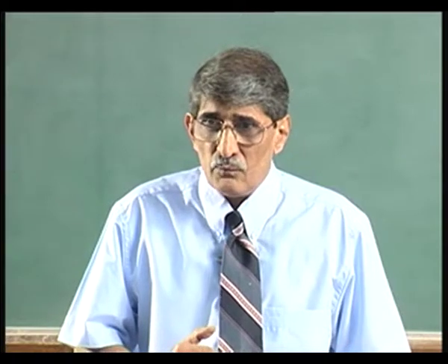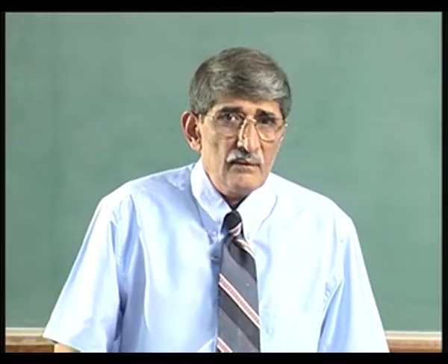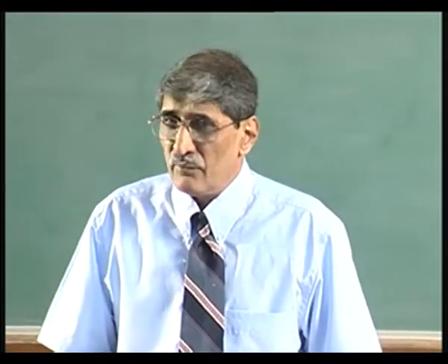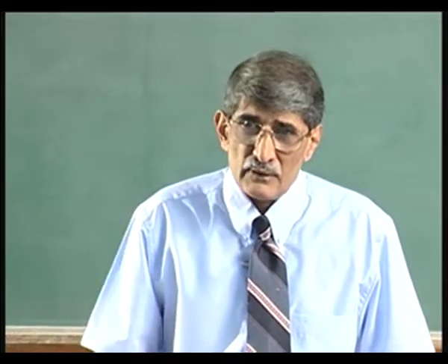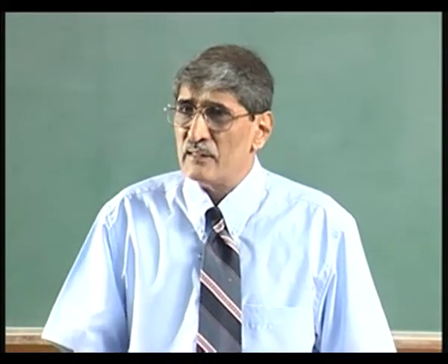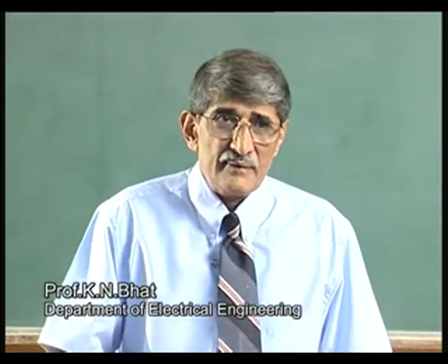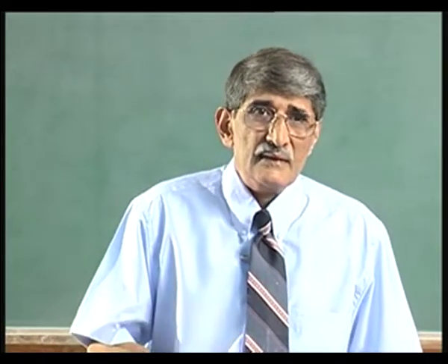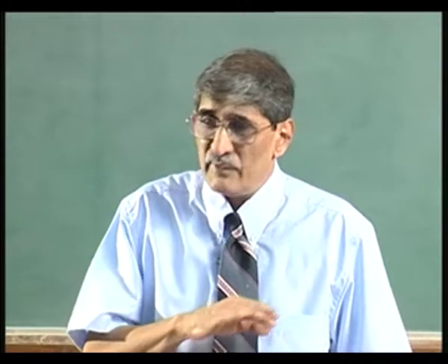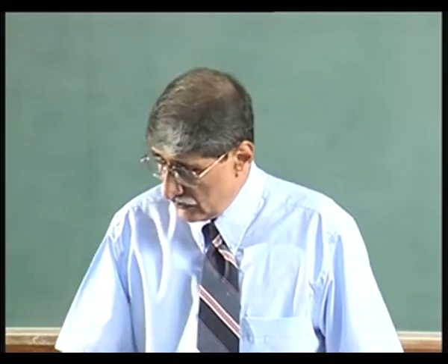Then we saw what are the dopants in these 3,5 compound semiconductors from second group, sixth group forming acceptors and donors, and fourth group behaving amphoteric way, but mostly going into the gallium site and indium site. And then we took a look at another aspect, that is the semi insulating material, which is important for high speed circuits. Then you can integrate the devices on a semi insulating substrate so that the routing capacitance can be reduced. And then we saw how to realize